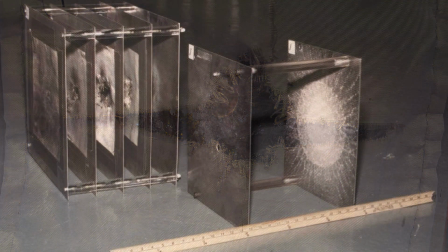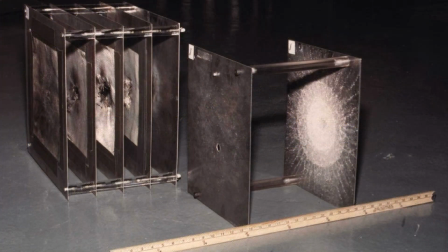A Whipple Shield is named for Professor Fred Whipple. It is a thin layer of material with a space in front of the protected surface. The meteorite will impact this shield and usually break apart, expending a lot of its kinetic energy. But Starship won't have a Whipple Shield as far as we know.